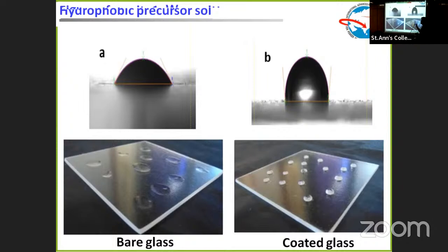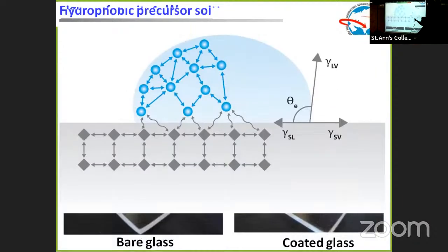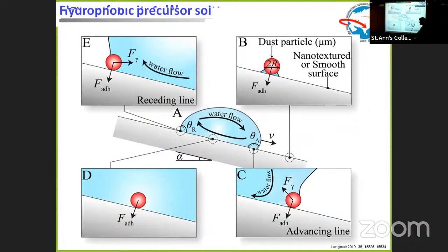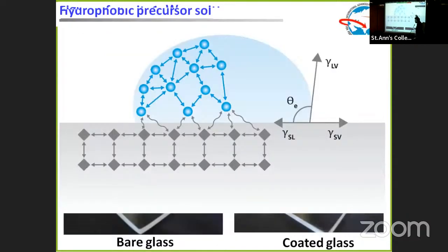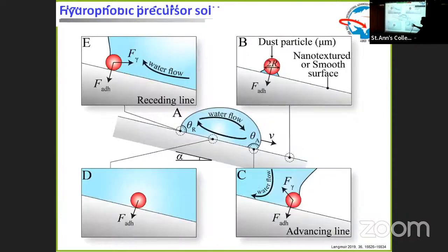Our initial attempt was retrofitting. We went to the plant and did it, so we didn't do all those tests. But now one of our technology receivers wants to try all those things so that we can integrate it in the production line. This is a typical mechanism of how the surface is pulling a water surface, so that instead of spreading, spherical droplets form on the top of that easy to clean, hydrophobic coated glass surface. This is the angle I mentioned, the water contact angle. And this is a typical mechanism. So just imagine that this is the glass plate kept at a different inclination alpha.